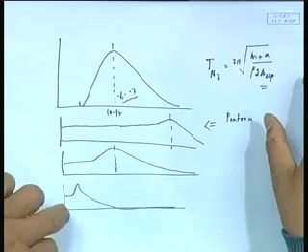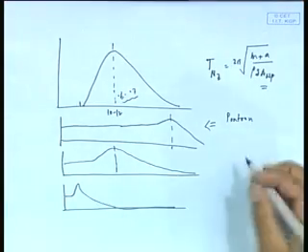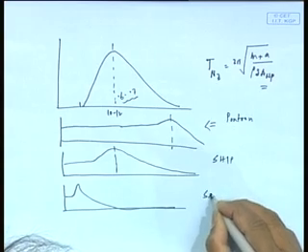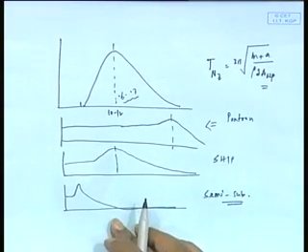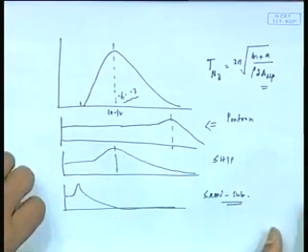This is the reason why you design this. Why you design this? There is a reason. This is a ship, this is a semi submersible. I have mentioned this also earlier, from an operation point of view, a semi submersible which is producing oil is not able to change location. That is point 1. Point 2 is that its operation demands that it has low motion, otherwise if it is heaving then you cannot operate, whereas a ship may not be so as such. So, therefore, you have to ensure by design that it has very low response.